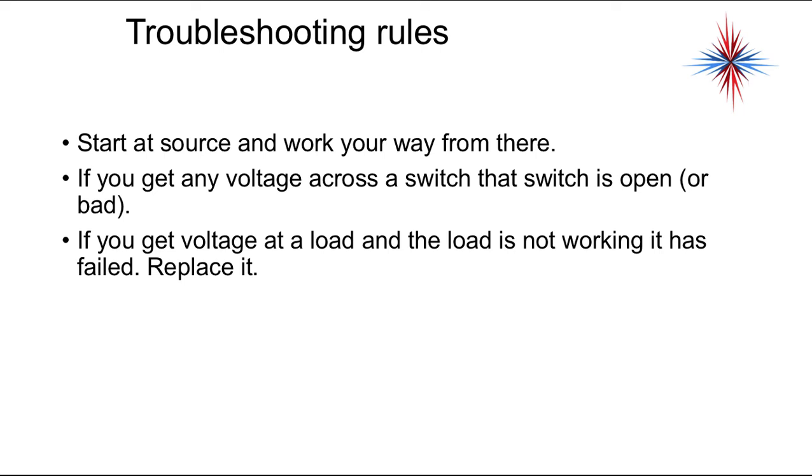Troubleshooting rules always apply. Start at source and work your way from there. If you get any voltage across a switch, that switch is open or bad. If you get voltage at a load and the load is not working, it has failed, replace it. Just a few extra notes.